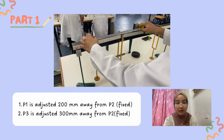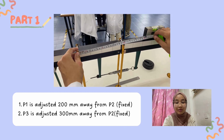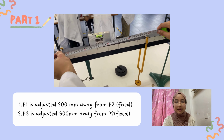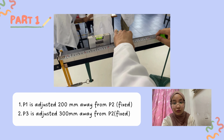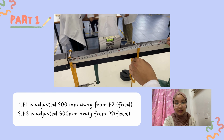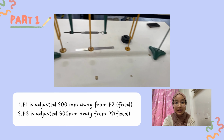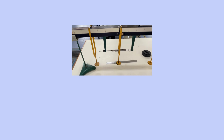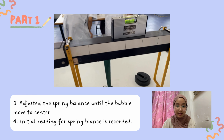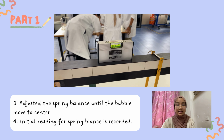For the first part, basically P1 is adjusted 200 millimeter away from P2, while P3 is adjusted 300 millimeter away from P2, where P2 is fixed. Then the spring balance is adjusted until the bubble moves to the center, and the initial reading for the spring balance is recorded.